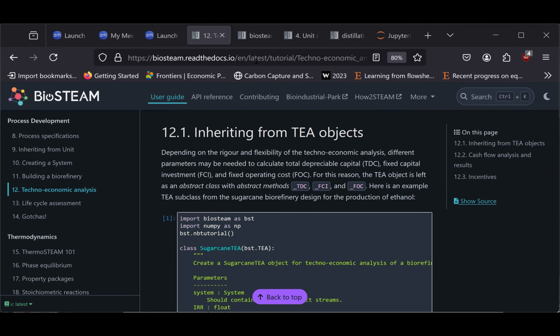Well, there are different phases for PCB recycling, with different combinations of phases. Some phases have to go through mechanical separation, so shredding. And there are other phases that would have to go through electrolysis, smelting, the furnace, and these kinds of things. So they will have some form of chemical reactions.